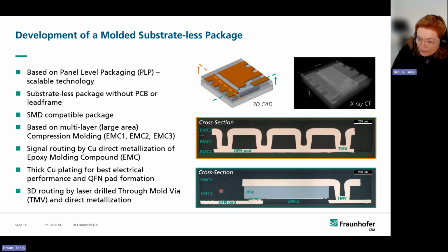And you see a little bit how that worked, and maybe you can also recognize, it was a 3-step molding process. In this case, the chips were overmolded the first time. The partner said they have so many stud bumping machines, so they did a copper stud bump and not a plated bump, but I think for the overall process flow that doesn't matter. So you overmolded that for the first time, did a grinding step so that you could also add the metallization on that top side.